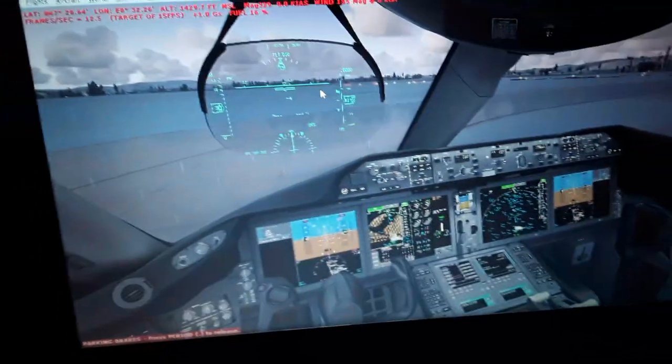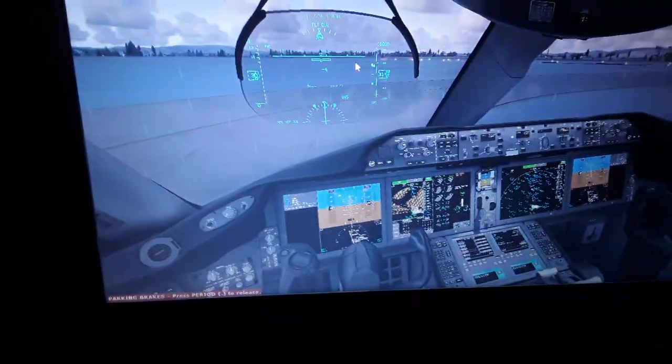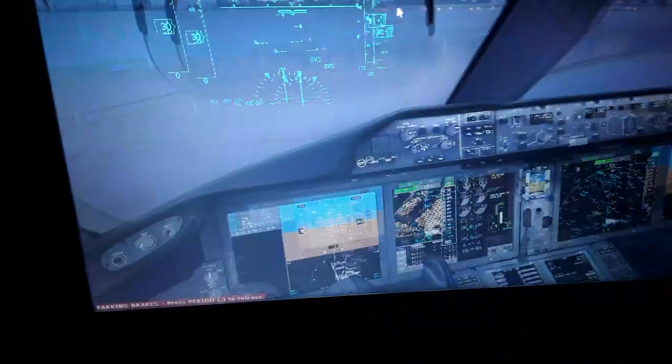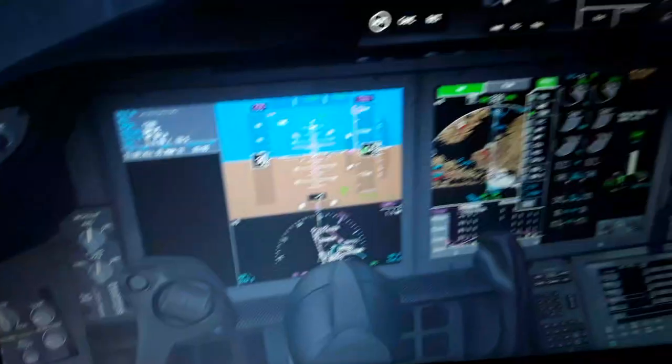So we're going to see we created a flight plan over here in the flight management computer. This is what we're going to use for navigation of the aircraft. So we can connect the autopilot flight director system panel. We will receive the VNAV navigation functions from the flight management computer data. So I'm going to show you also that. I'm going to show you now the flight plan created in the primary flight display. So I use, as I told you, the takeoff gross weight of the aircraft. I will make the explanation of the system.